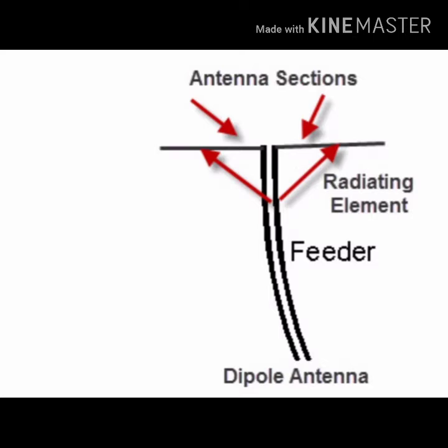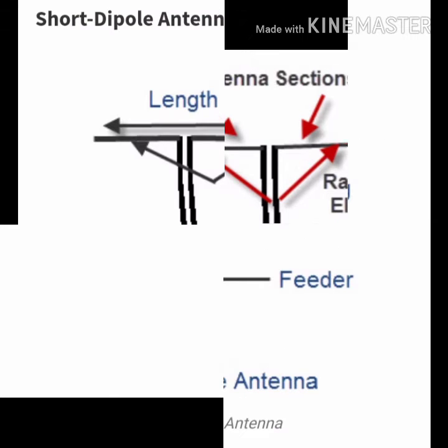Dipole antenna. A dipole antenna is one of the most straightforward antenna alignments. This dipole antenna consists of two thin metal rods with a sinusoidal voltage difference between them. The length of the rods is chosen in such a way that they have a quarter length of the wavelength of operational frequencies. These antennas are used in designing their own antennas or other antennas. They are very simple to construct and use.